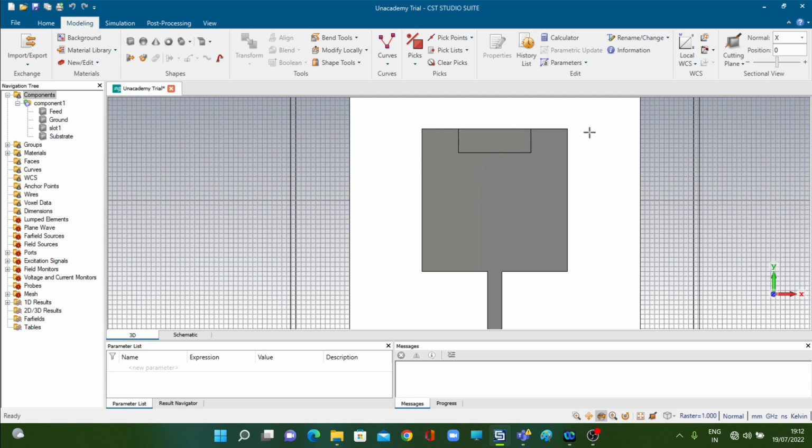Compact means small structure, electrically small structure. So keeping that design motive in mind, we can't make the structure too large. But at the same time, we wish to do that to increase the path length for the current so that we can have an enhancement of the bandwidth. So these two requirements are basically contradicting.